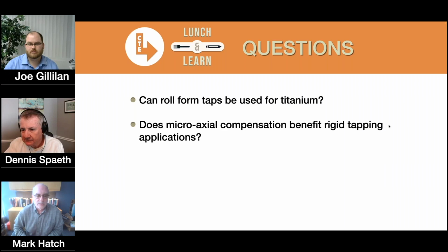But as you get into larger diameters and coarser thread pitches, say we start getting into 3/8-16s, 7/16-14s, 1/2-13s, here the load becomes very, very problematic, and also the displacement of the material much more difficult because of the size of the chip section or the material section that we're dealing with. And then also that split crest at the minor diameter, which can be restricted in many components.